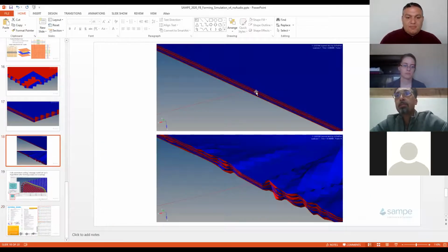We can see here, for example, where we attach the spring on the edge of the structure, and when we stretch the material based on the stacking sequence, let's say, for example, in the blue we have plus or minus 45, in the red is 0/90. Each layer acts in different ways, so starts to buckle differently, right? So how can we predict that and how can we simulate that?